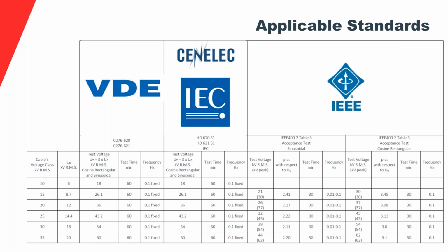And now with the latest generation cable, the tree retardant XLPE, which was introduced in the early 90s, and the EPR, by the way, just to get this out of the way, EPR is also treeing, it's comparable to tree retardant XLPE, the tree rate. And so these trees will grow over time naturally if you have moisture in the cable.